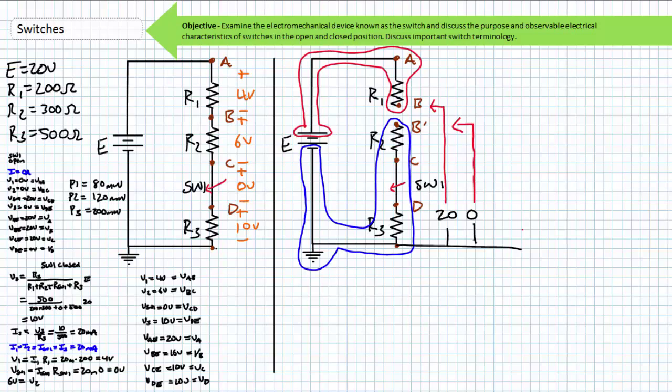Between two components ordinarily connected to the same node, there is a voltage differential. You found the problem. This is the open circuit, and no current will flow through it. Beyond the systematic inspection of a series path using a voltmeter, an incredibly handy bit of advice in resolving open circuits is to just look at the circuit. Close inspection will often yield an off by one error, a severed wire, or a wire just dangling off in space. Take necessary safety precautions when troubleshooting such open circuits, lest you become part of the circuit.